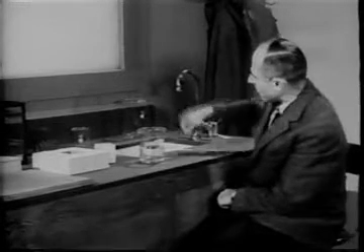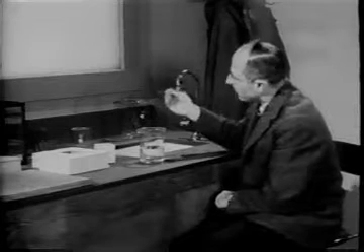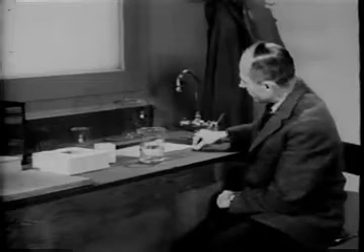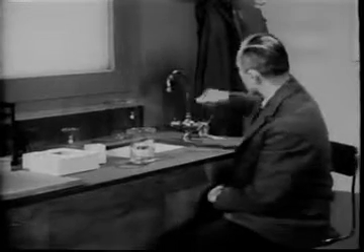Let us think of a very small lump of fluid, smaller even than this droplet, which nevertheless contains many molecules. The average density is defined as the total mass of all the molecules of the lump to the total volume of all the molecules with their surrounding space. Density is mass divided by volume. But each lump or particle of fluid may have different properties. For example, not all particles have the same motion, as you can see by looking at the flow in a sink.